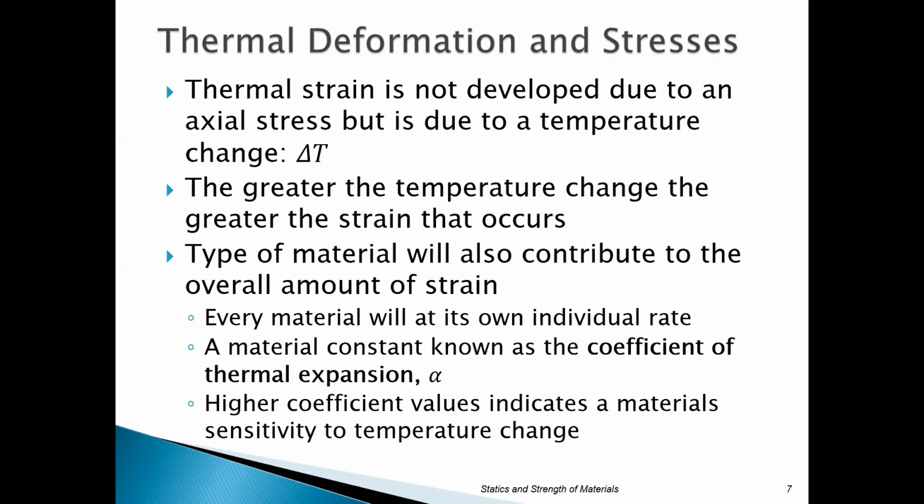And it's kind of like when we talk about strength of material. When we talk about modulus of elasticity, those slopes of those lines are defined based on that material as well. And they mean something: a higher slope means an object is more rigid, but with a higher alpha, that material is more sensitive to temperature change.